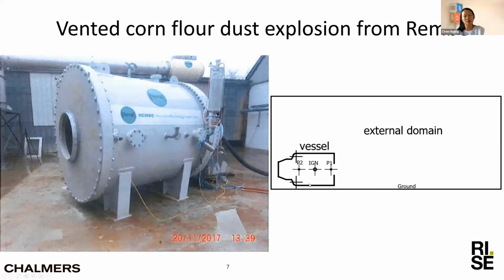Then the dust air mixture is ignited in the middle of the vessel with a pyrotechnical igniter, and they measure the pressure development inside the vessel.